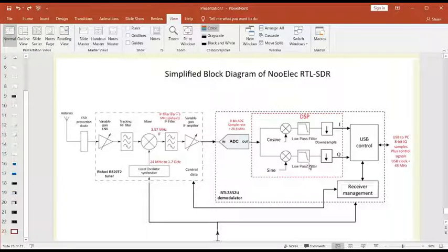So here's an interesting thing. This A to D here is always running at 28 megahertz, but the GUI said the IQ effective rate was coming in at 2.4 megahertz. So that is what these two blocks here with the down-looking arrow are. They indicate down sample, so they are reducing the data rate that's coming into the USB port on your computer.